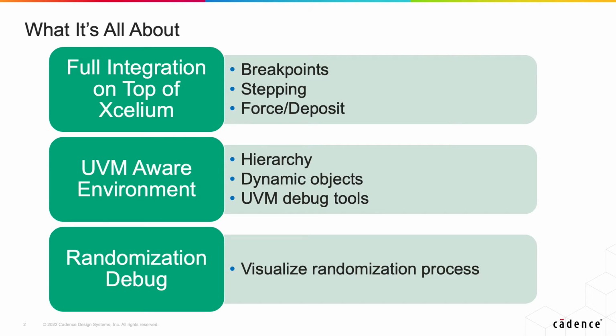We have three pillars. First and foremost, the integration on top of Xcelium. This allows us to place breakpoints on the code, and from the point we get to it, step by step, go over the source code. Of course, this allows us to place forces and deposit while simulation is running.